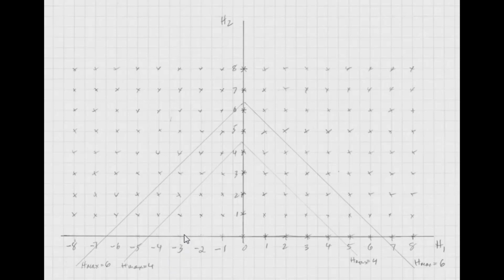Okay, now, if I say, again, that we want 8 harmonics of F1 and 8 harmonics of F2, we get this frequency set, this whole big thing here. You may not really need that many frequency components, frankly. You may only need orders going up to 9 or 10 or even less than that. So what do you do about that?